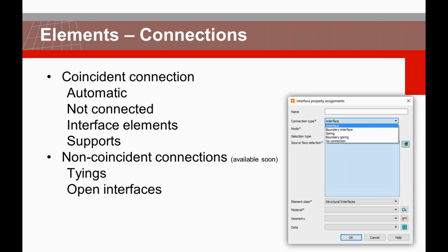What we have enhanced in the interface element also is based on the projection. So if you have 2 bodies that there is a gap in between, you can use the new feature and generate interface in between the gapped areas. So that's very intuitive and useful when you are modeling, for instance, a beam and floor, and you're dealing with the offset of the neutral axis. So your beam and your floor, they have a gap, and the connection of that can be easily defined based on the new interface modeling feature that we have in DIANA 10.1.